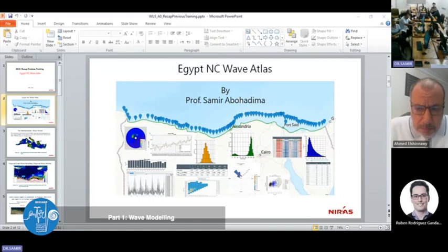This is one of the analyses, as an example, the annual average and long-term monthly pattern at the Delta coast. This shows the mean water level due to surge with time for the 41 years, which shows that there is a linear increase, and we can detect the equation using Excel. The source of the data? This is the results of the model. The regional model.